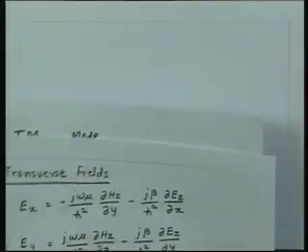Of course, your conclusion might be different when we go to the transverse electric case, but these are the conclusions which we can draw now for a transverse magnetic case. Once we get this Ez, then we can substitute for Ez into these components, and then we can write down the transverse components for the TM mode.